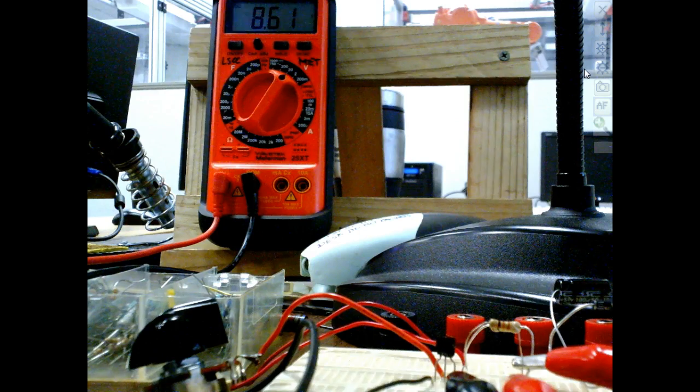You have no problem. In an amplifier, though, you're running that in the active region, so it's not acting like a switch anymore. It's acting like a rheostat, but the rheostat is changing with temperature. That would be awful in an amplifier circuit. So next we're going to get into the way we can bias, what we call voltage divider bias, where it is going to be steady no matter what temperature you're running at. So we can bias it in a way where temperature won't affect it. And that's what I'm trying to get to.